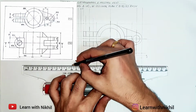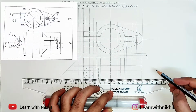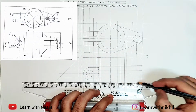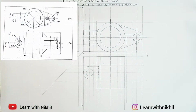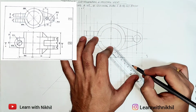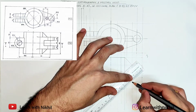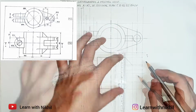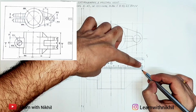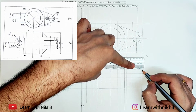Now extending this and the 45-degree angle line, as we have to take for the right hand side view. So I am already extending them towards the 45-degree angle line as we are progressing with the sum. Now this is the slant line, so I am drawing it. This slant line in the front view we have drawn, that is hidden. Joining this part dark. After the section, this part will be visible and dark.